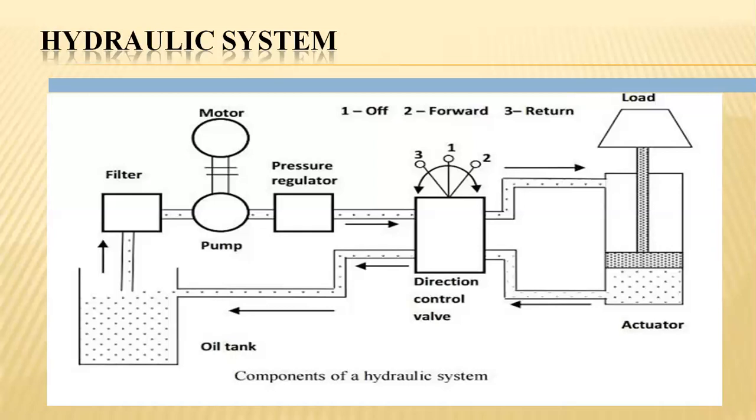Hence, the operational process is considered for both the extension movement. In order to lift the weight from the bottom dead center to the top dead center, the piston needs to make a movement. For this condition, the second position needs to come into existence. That is the forward stroke. Hence, the fluid enters crosswise in this direction and lifting of the load takes place.